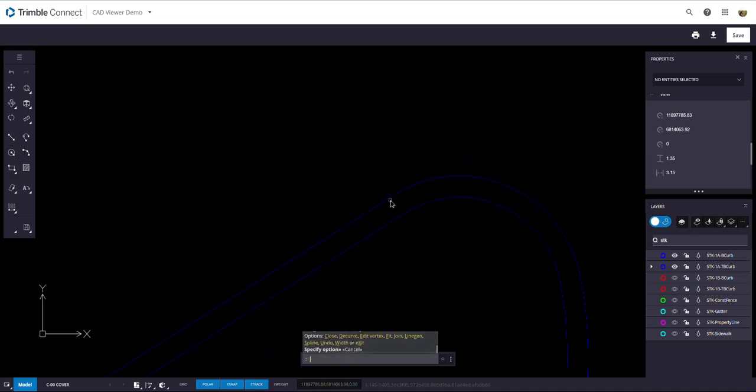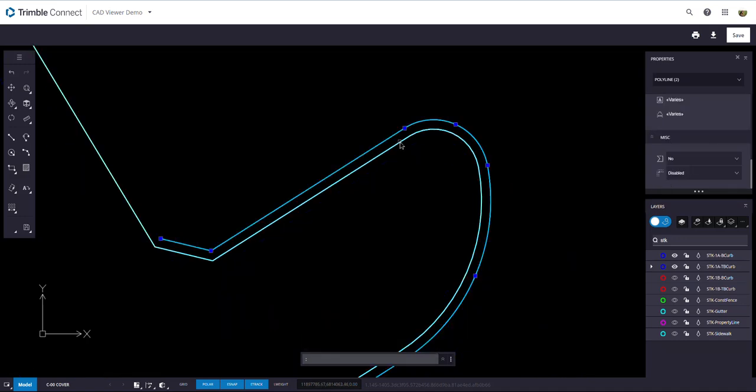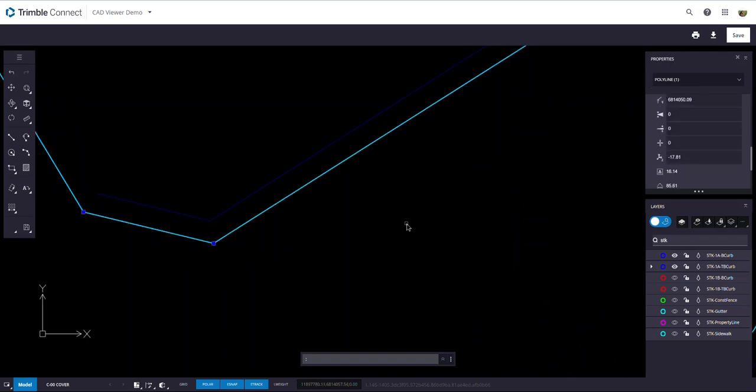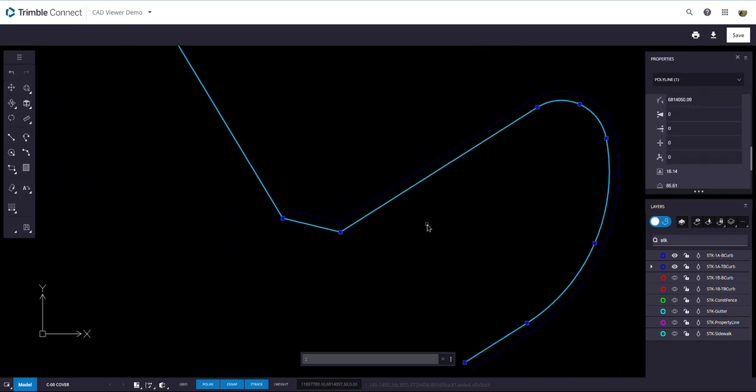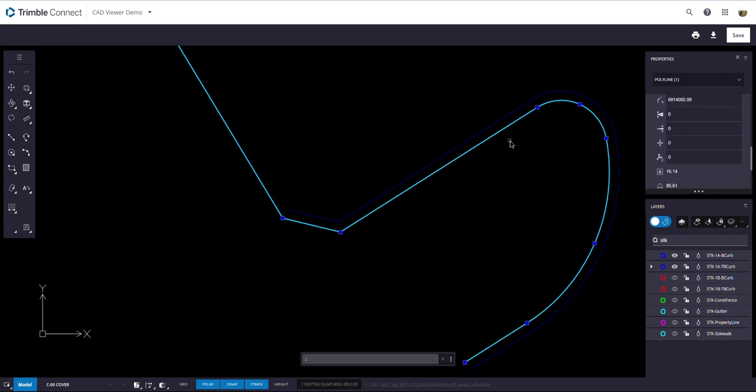So instead of fighting this, what I'm going to do is pick those two lines. Let's pick this line and make sure we set that one to 0. Okay, so we'll make sure that one's 0. Since this is a good line, we know we're going to break it here. Let's try the offset command. That way we don't have to fight with trying to get it to join.